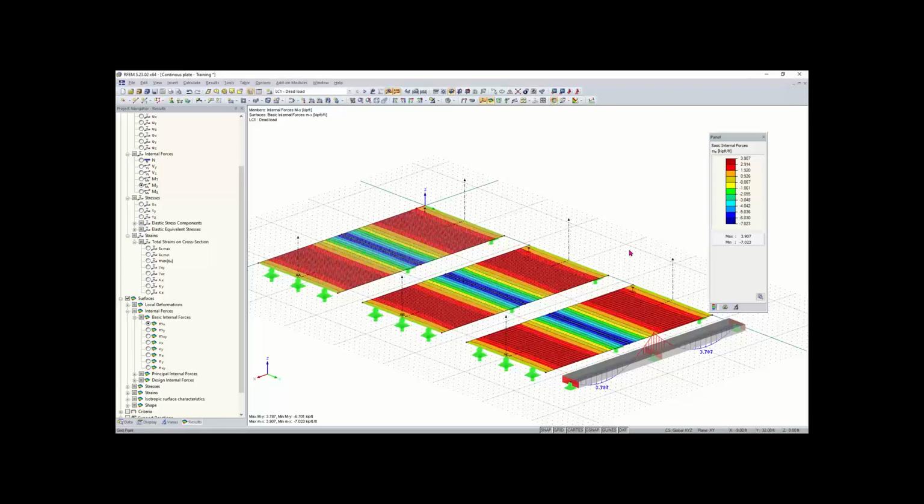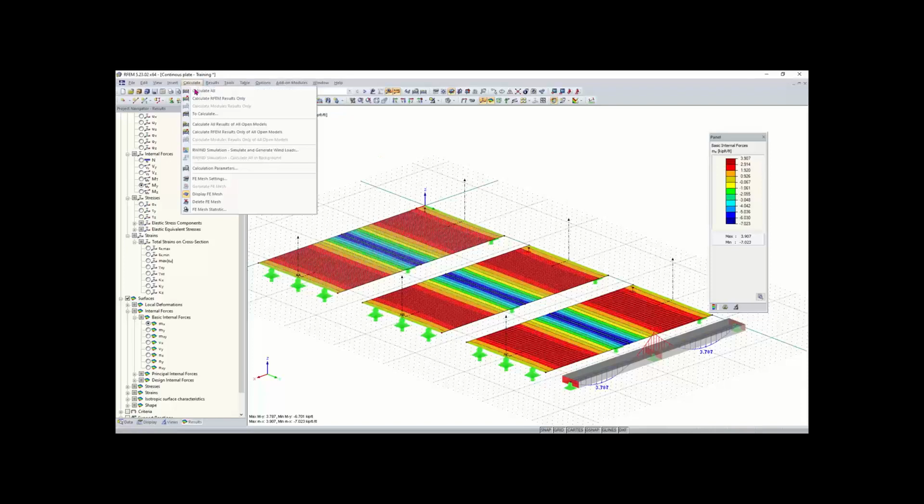Yeah, I think exactly as Alex had mentioned, it's basically just running a test and trial type process where you continue to decrease the FE mesh size. And exactly as he says, if your results are changing significantly, then you know your FE mesh is not refined enough. The other thing I wanted to point out, if Alex, you can go to calculate FE mesh settings again.